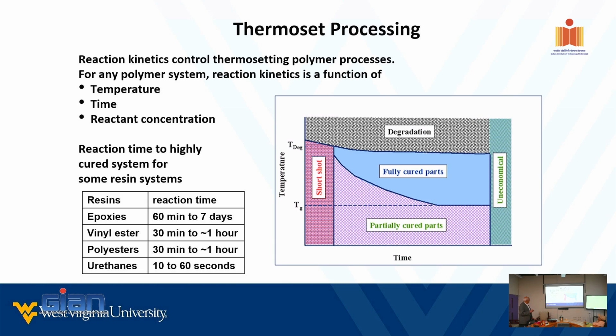That depends on the resin system. If I go much further, it becomes a flowable zone. So we do not, under any condition, want to go much above Tg, the glass transition temperature, minus 20 degrees F. In other words, if it is 210 degrees, I want to operate as much as I can below 180, 185 degrees. If I can go, but the properties are going to degrade.